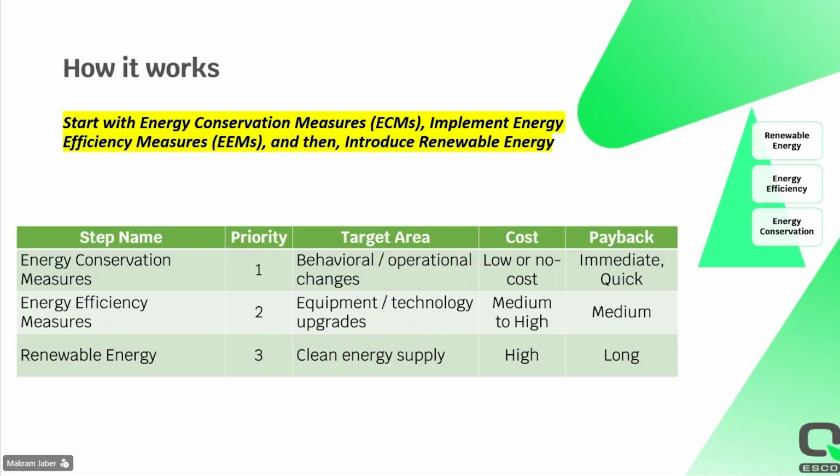While the energy efficiency measures are related more to the equipment themselves, like the chillers and the split units, replacing and controlling them, most updates are related to upgrades in technology. For example, the conventional split units were on-off units, while now we have the inverter unit.